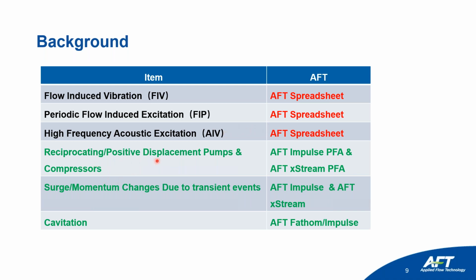Reciprocating positive displacement pumps and compressors are already addressed by AFD Impulse PFA and AFD Extreme PFA. One is for incompressible flow, one is for compressible flow. Surge and momentum changes due to transient events are addressed by AFD Impulse and AFD Extreme for compressible flow. Cavitation is addressed by AFD Fathom and AFD Impulse.